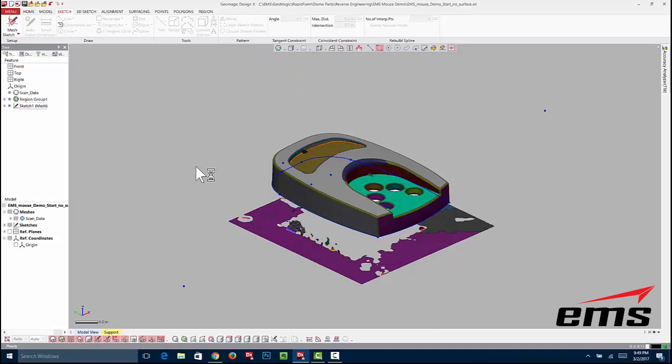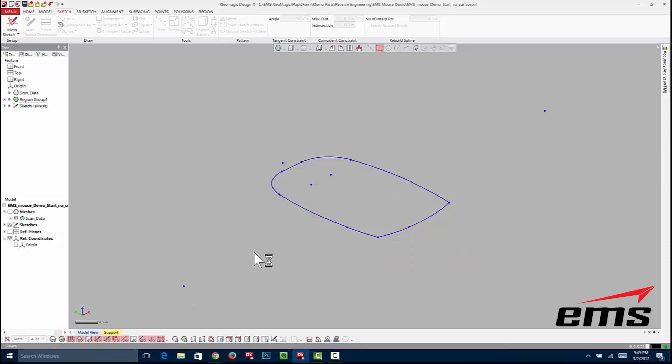So just to review, I created what we call a reference sketch, and then I built an actual sketch from that scan data. So if you turn off the mesh data and you look over here in our tree, just like in any CAD system, this is all history-based or feature modeling. That is my first entity. So there's my scan data, my region group, and then my first CAD entity, which is the sketch. Okay. So let's turn back on our scan data.